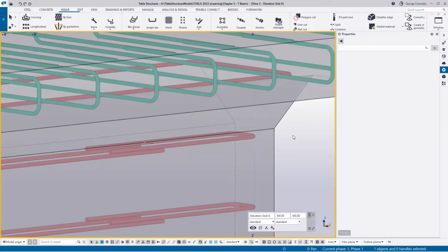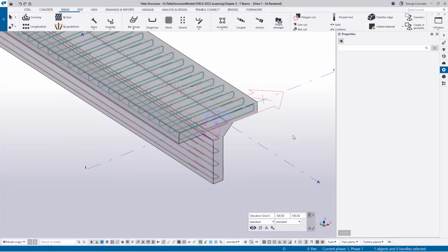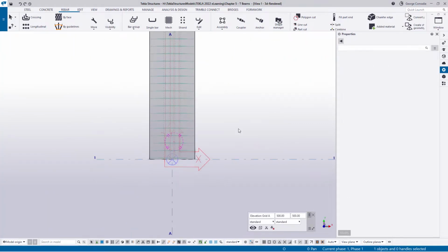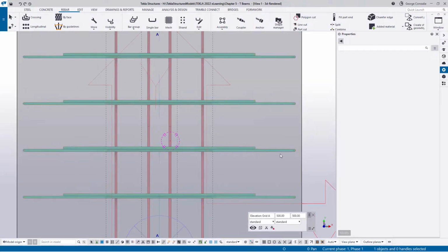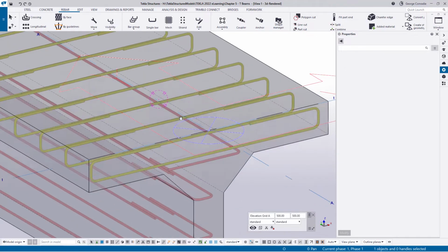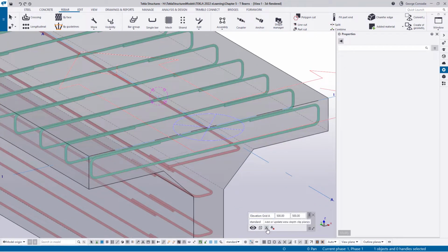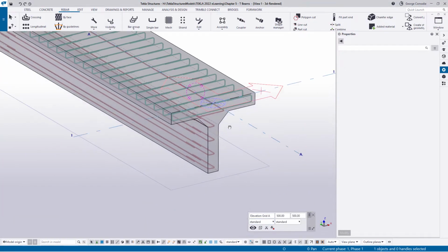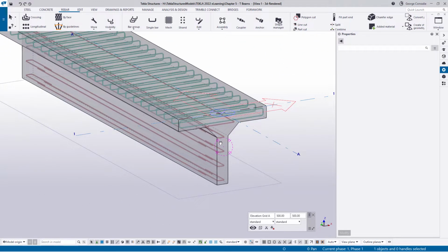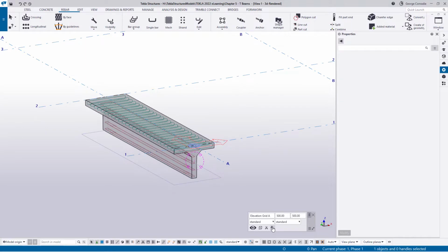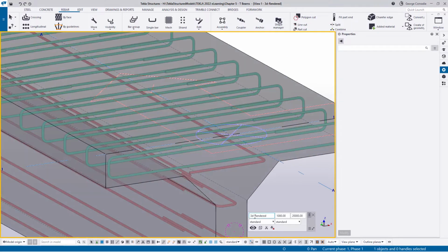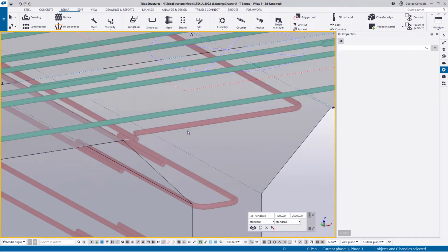And now if we go to the top view and we go Control P to see it, and we zoom in a bit, we should see them there. We don't. If we don't see them, if we hit this little scissors here, it will show us our depth of range, and it looks like we don't have a problem. The depth of range is good. Oh, there we go.